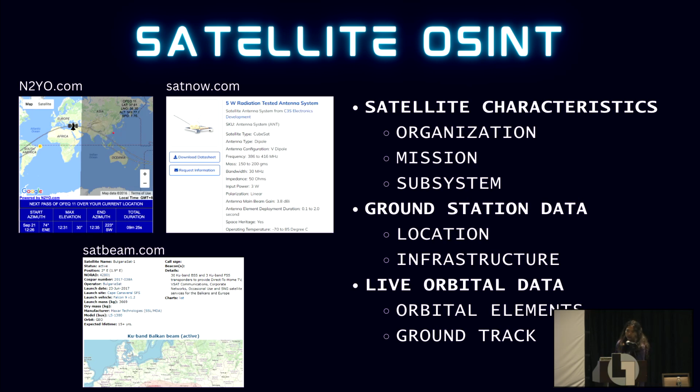And core characteristics that I look for whenever I'm trying to audit for a target satellite include the organization it's affiliated with, any launch slot providers it might be affiliated with, if it's an AMSAT, alongside the mission criteria. Oftentimes the mission will determine what kind of payload information it might be sending out, or the structure of the telecommands you're trying to send via the uplink to the satellite, alongside subsystem information.